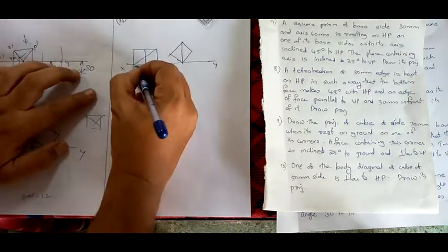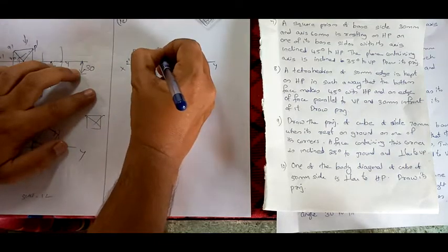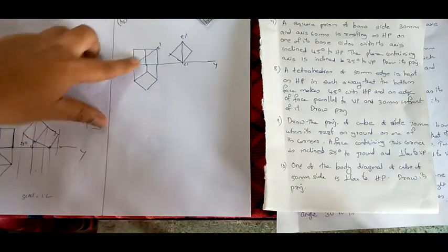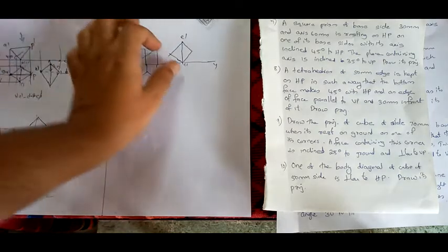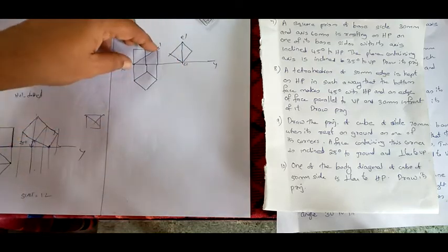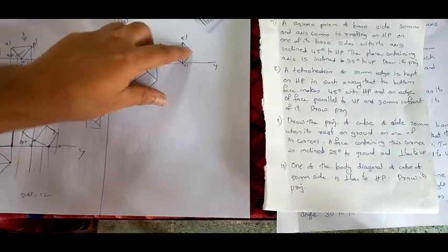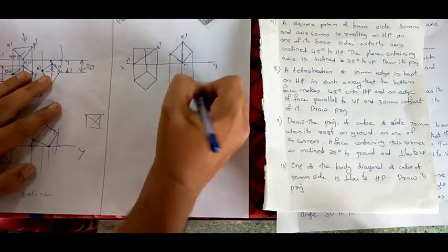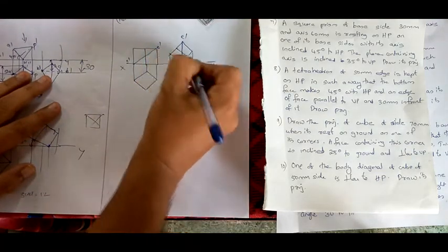So draw this, if this is C dash E dash, I am simply saying, then take C dash E dash perpendicular, then what you have to do, take this on the compass, cut an arc here, take this on the compass, cut an arc here, you can complete this one. Similarly, after completing this, draw perpendiculars and complete the square and then obtain the corresponding views. One more is coming here.